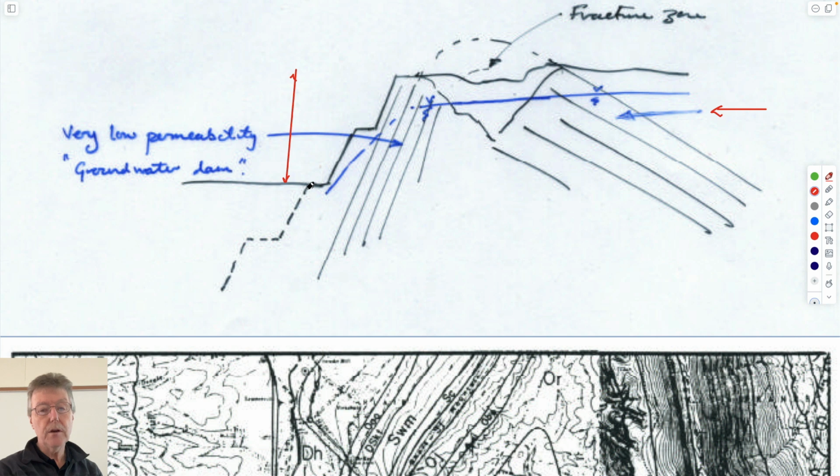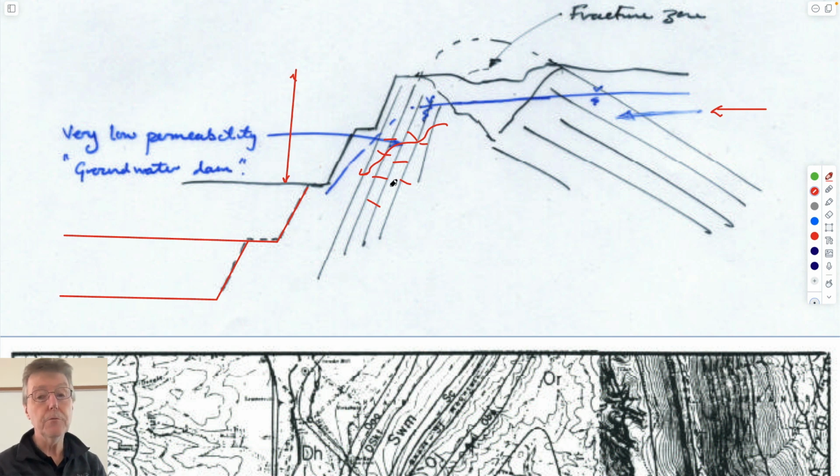The worry was that if you deepen this by creating extra benches sequentially, you'll allow all these rocks to move and displace, to fracture, and all of a sudden the groundwater dam, which was very effective in piling up the water behind it, will allow water to come through, and all of a sudden the spring, which was flowing in Roaring Spring, won't flow anymore.